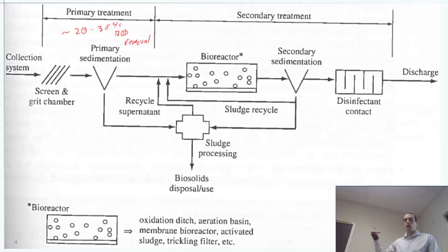We're going to move on later after the wastewater treatment. After we flesh that out, we'll go on to take a look at modeling oxygen demand downstream. But you guys have already heard about the concept plenty, I'm sure. Okay, so then that would be primary treatment. The junk that we collect will go to a sludge processing. We'll probably directly landfill from here, actually, collect the solids.